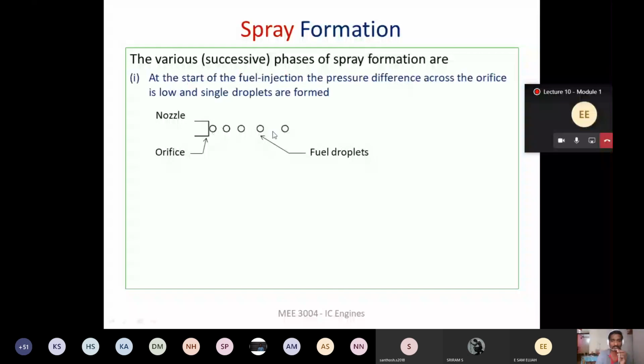So we will get almost 4 to 5 droplets of fuel sprayed into the engine cylinder. And subsequently, there will be a continuous flow of this fuel in the form of liquid, to a certain extent. This is after the droplet formation, then we'll have the continuous liquid, right? To a certain distance. Then after that, that continuity will break. Okay. So this we call the breakup distance. I will tell you the breakup distance in detail.